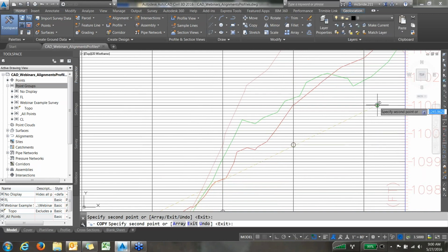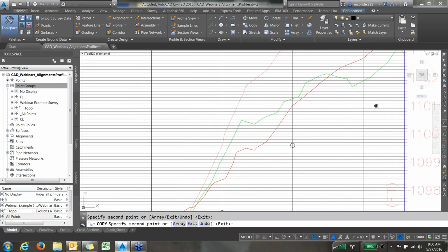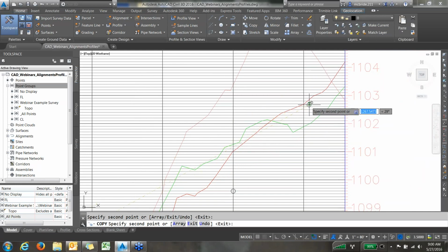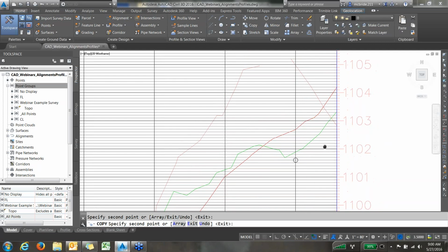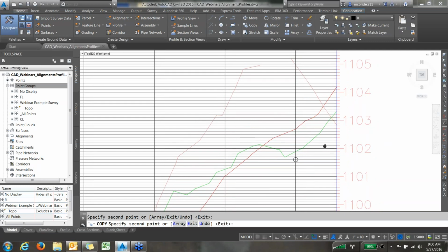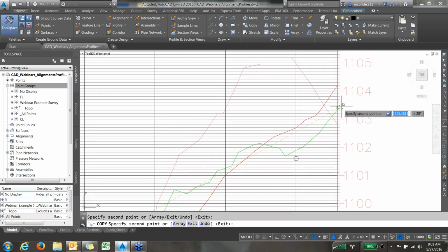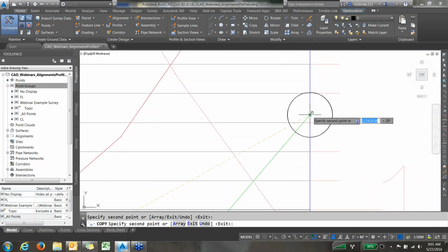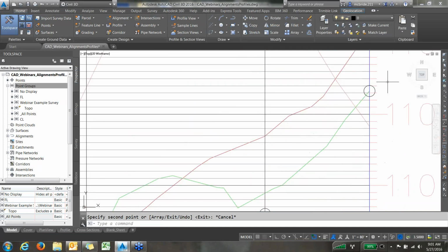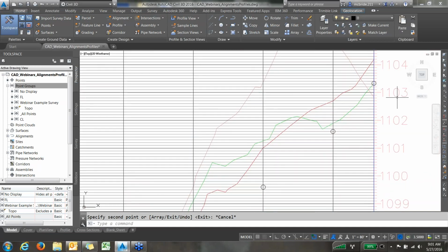Okay, now in this case over here, the two low banks are higher than my grade line and almost to the point to where I don't have to go 1.2 foot below the low bank. It may be somewhere down here, but it's closer to the existing ground, which is good because I have to daylight my top end of the grass waterway. And to do that, I'm going to zoom in to where the existing ground is and put my last circle. Okay, now if I zoom out of this, you should see below the grade line all these circles.